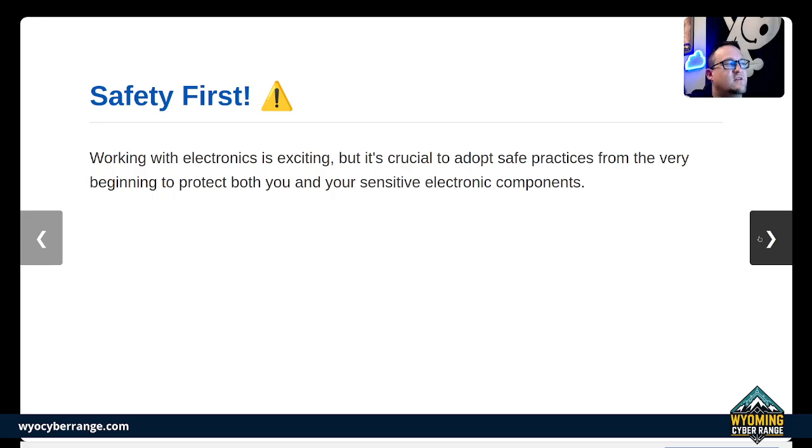Okay, so make sure that you're unplugging your stuff, and then also I always try to recommend make sure that you're using a surface that isn't going to conduct electricity. For instance, I like to use rubber mats or grounding wires to make sure that I'm not wearing socks and walking across the floor and getting a static shock to my devices, because that's the easiest way that you're going to kill the device and, well, it's going to be a paperweight at that point.